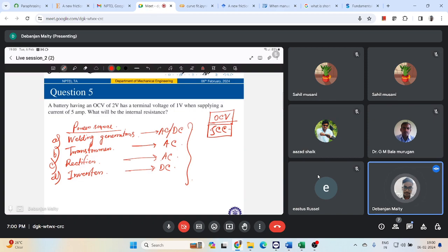When there is no load, or no current flowing between the electrode and workpiece, or the positive and negative terminals, the voltage that appears at the terminal is at its maximum. So at no load condition, the voltage at the terminal is called OCV, or open circuit voltage, which will always be at its maximum.